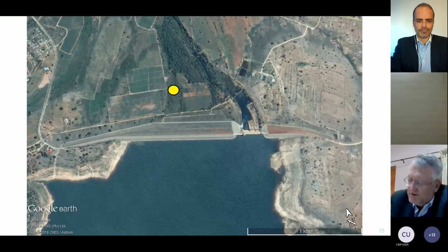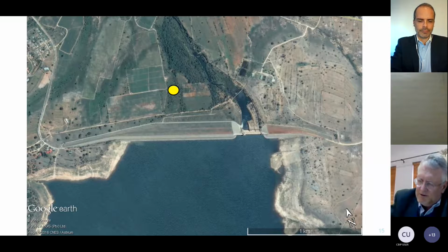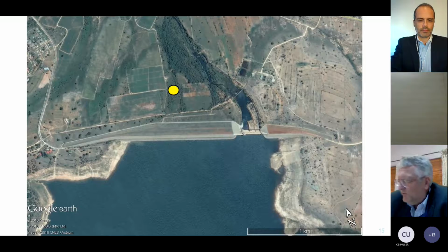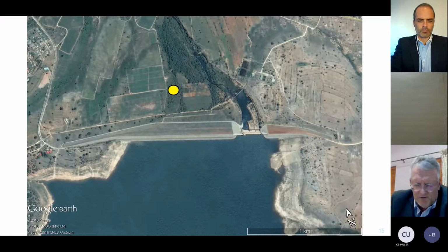The interesting thing is the methodology of construction; it's important that one understands it. Because of the alluvial layer, it did not have a lot of density, so they decided to do dynamic compaction on this alluvial layer as well. They first installed the pressure relief wells, then they did the dynamic compaction, and after that they did the grouting, and then they built the embankment on top of that.